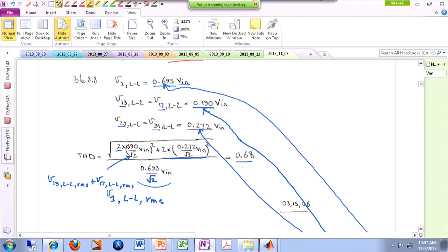and it's not actually a good number, which is a good point over here: total harmonic distortion by itself is not really a good indicator of how good your signal is. The other factor that you have to pay attention to is at what frequencies do these harmonics appear. Now the good news over here is the undesired harmonics are at very, very high frequency. So I have this fundamental harmonic here, and then the first bothering harmonic is at 13. So I can easily filter this thing out.